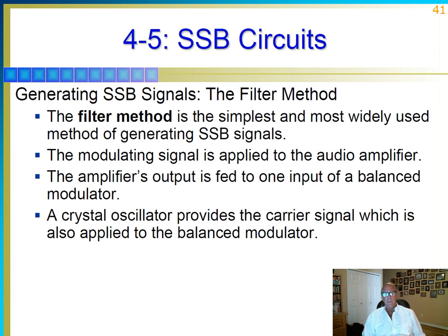And to generate SSB, go ahead, use a lattice modulator and filter out either the lower sideband or upper sideband. Okay.